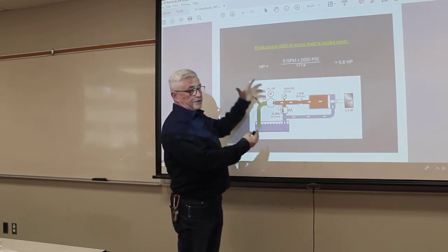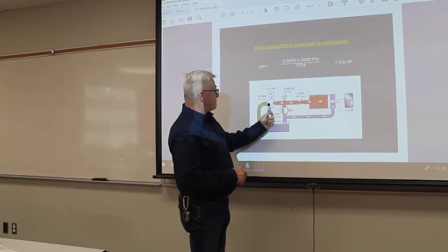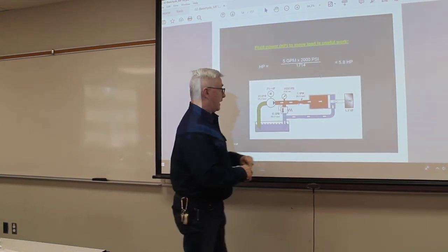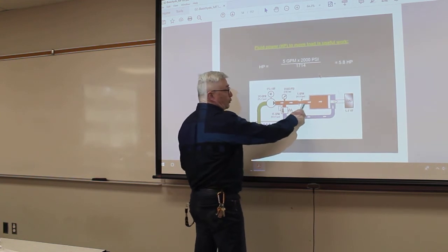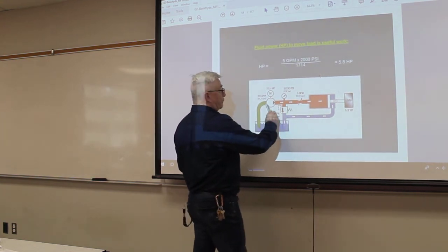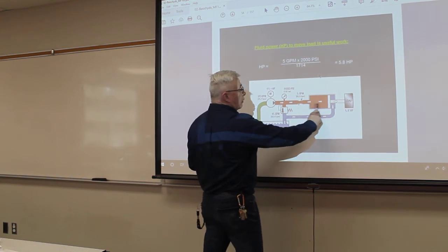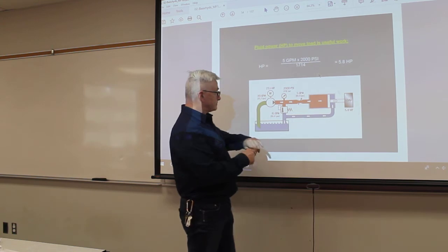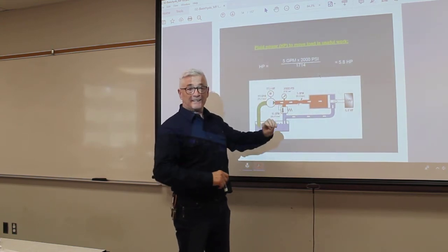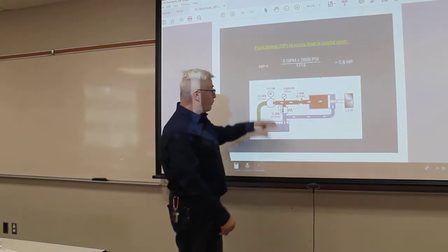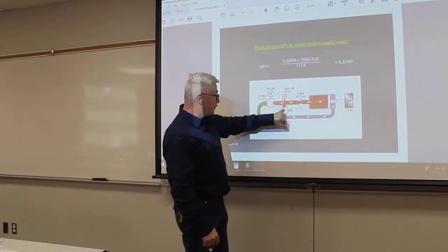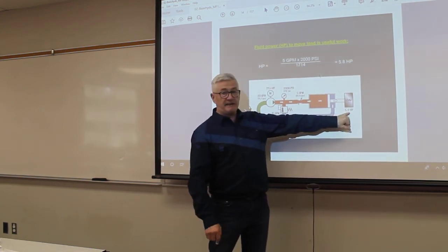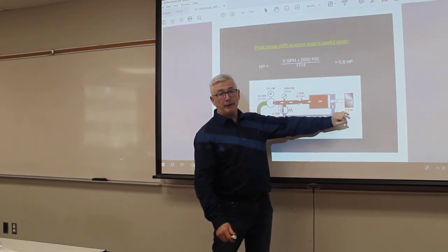each of these pictures gets a little bit more advanced. We maintain the 20 gallons per minute. We maintain the 2,000 psi. But now we put a variable flow restriction onto this, and of the 20 gallons we're putting out, we are only going to use 5 gallons to move the piston out against the load. The other 15 gallons that the pump created must be returned. So we return 15 gallons directly back to here. And we're really only using 5.8 horsepower to actually do any real work.